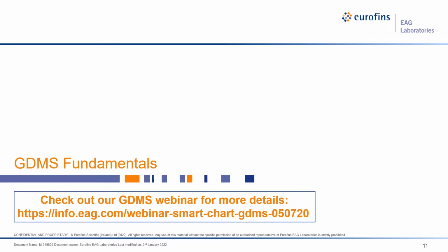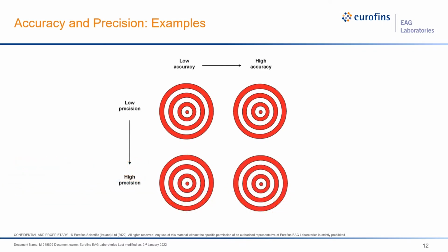For any technique, we have to deal with two things in measurement. It requires dealing with precision. It requires dealing with accuracy. The precision is how well the measurement repeats itself, and accuracy means how far off the measured value is from the true value. There are four scenarios we're dealing with.